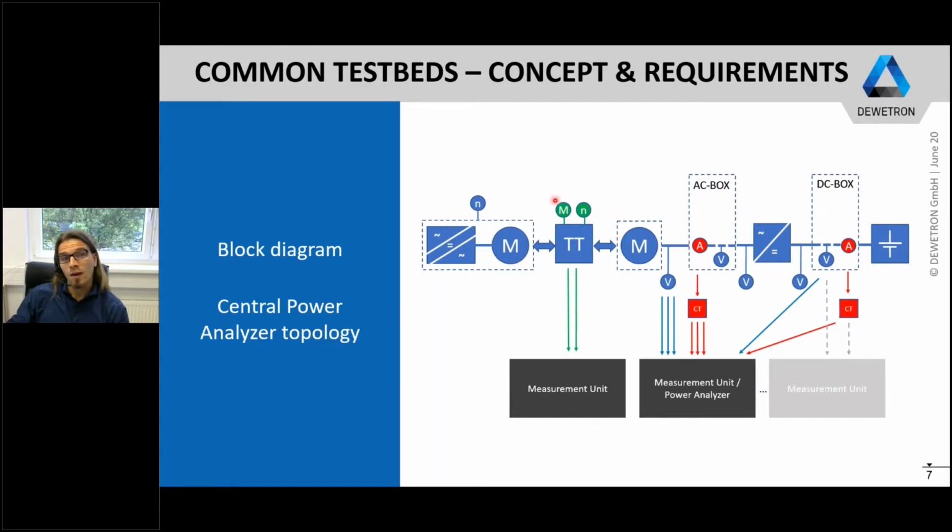So you also want to acquire the torque and the rotational speed of the motor, and therefore you often need an additional measurement unit for analyzing the mechanical efficiency. Then for analyzing the efficiency of a three-phase motor, you often need already 3 different measurement units, even for this easy test setup.